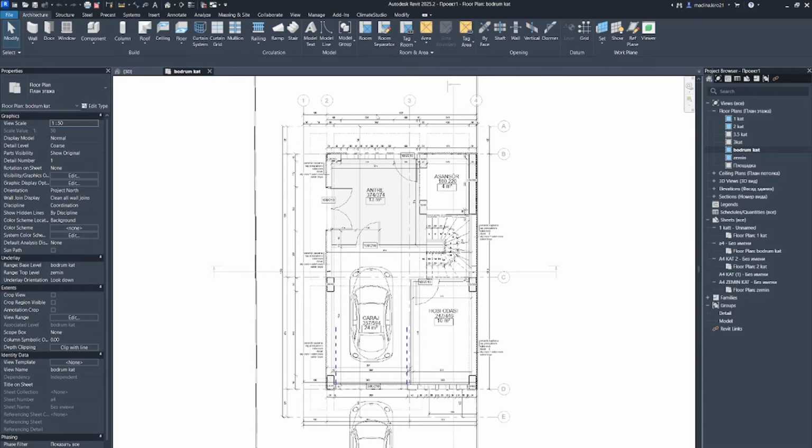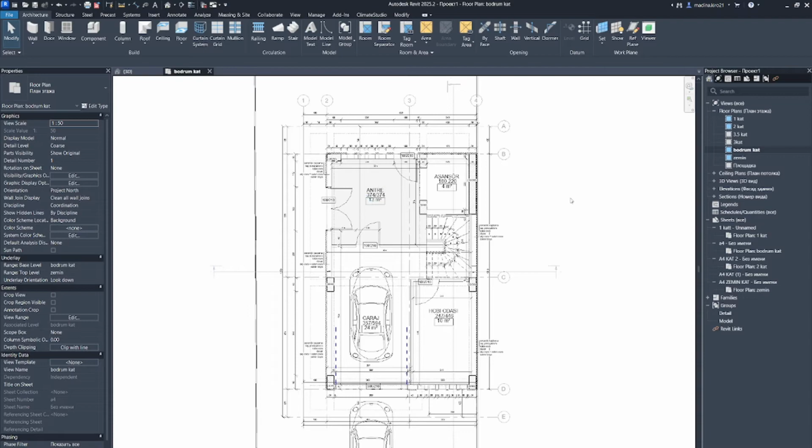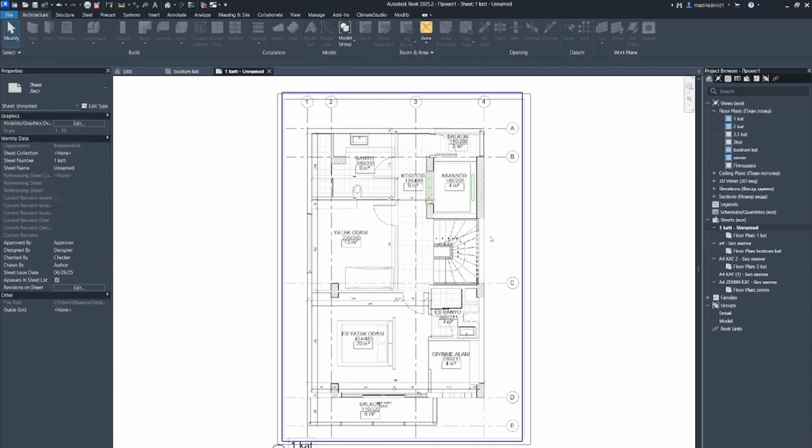What I'm going to start with is the scale which we have here. For me it's 1:50, 1 divided by 50. What does it mean? If I make it bigger, then my writing is going to change. This is not what we want. So before adding details, you have to make sure which size of paper you are going to use. For me, I'm going to open sheets. I'm going to use A4 format of paper, which is actually small.